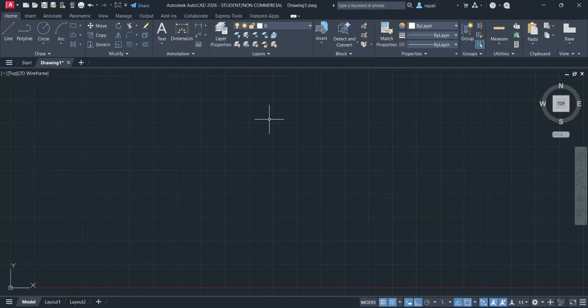When they are inactive and let's say you are drawing a line, it will be very difficult for you to know that that point is your endpoint, that point is your midpoint. So it is good for you to make sure that all of these O snaps are active so that it will make it easier for you to draw.